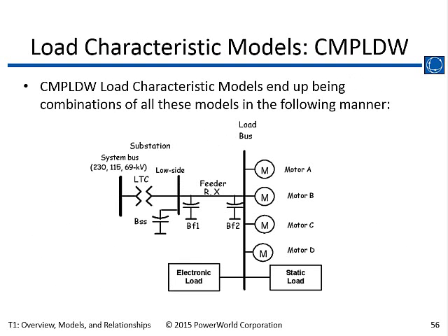Talking about complexity, we used to have for a load just one load there. Maybe it had some voltage dependence in it. Maybe it had a 30% induction motor load. Now where WECC is going is to treat the load as it really is, getting close to where it really is. What's sitting behind that innocent little load at, let's say, a 230 kV bus or a 115 kV bus is a transformer. There's maybe capacitors embedded in there.